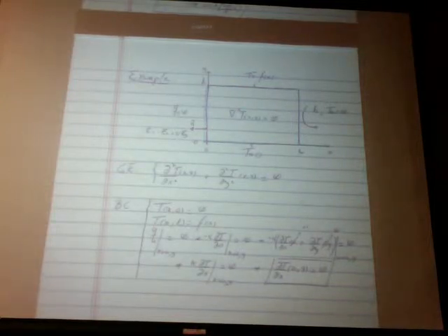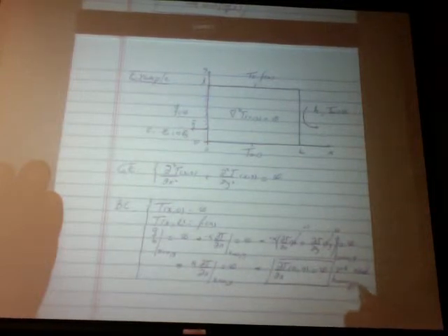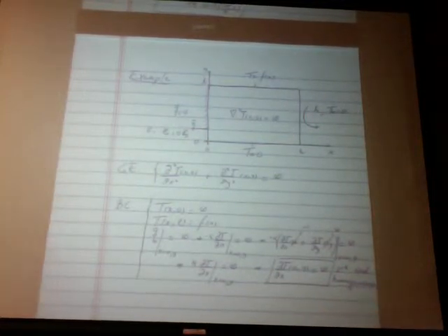In this case, a heat flux that is imposed is equal to 0. This is second kind, homogeneous. Remember, the second kind conditions are also called Neumann or natural. And in heat transfer, we refer to them as flux conditions.